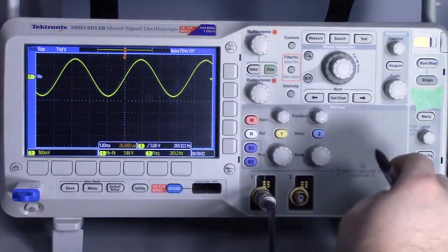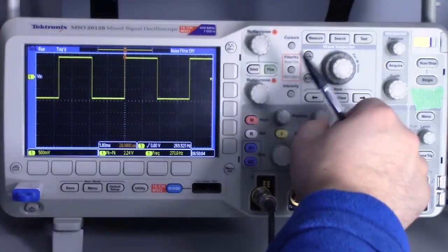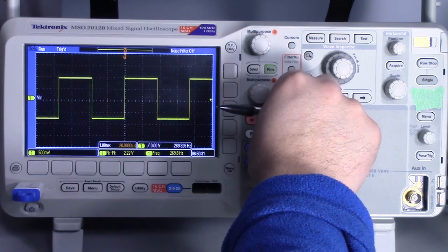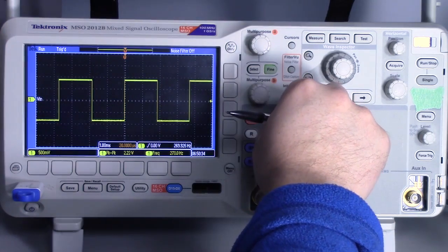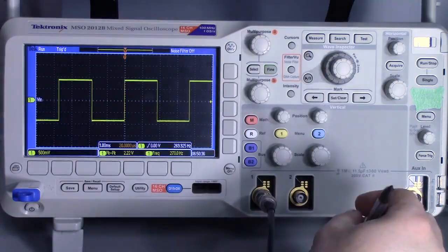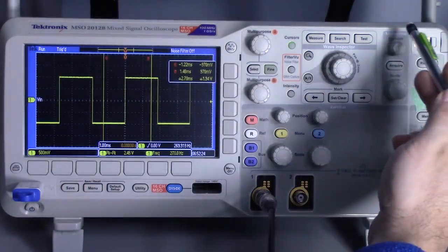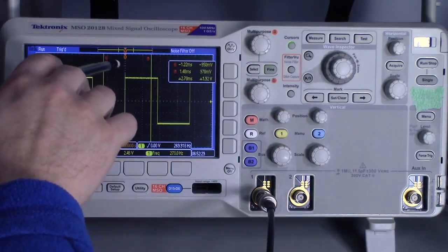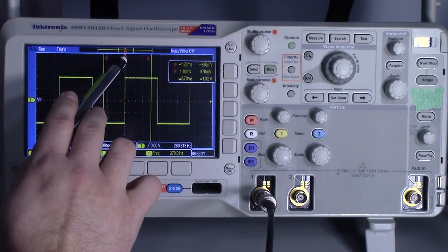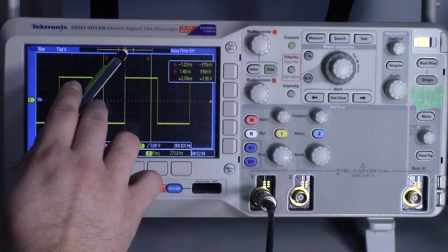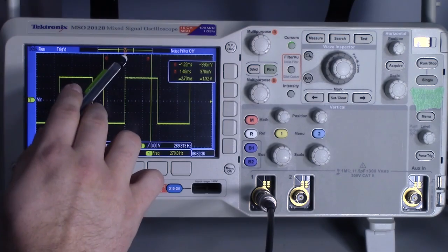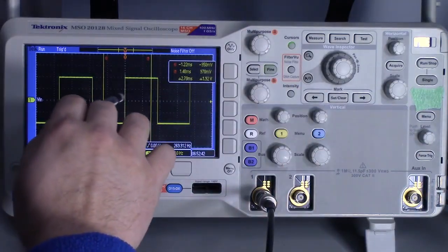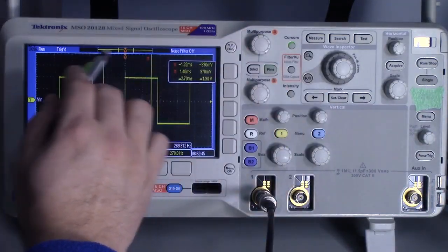Let's say, for example, I want to measure a square wave. So we'll just move this down and we'll line it up. Also, in the horizontal, you can change the position of the trigger point. So you can see right up here on the screen there's a T, and it kind of points the arrow. So this is the point. This is your time equals 0. This is whatever you set your trigger level at, that's where it starts. So we can actually move this left and right.